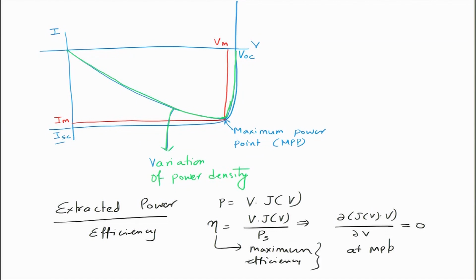Okay. So, this is how these two are going to vary. Your efficiency will also follow a similar kind of curve at this point. So, your efficiency will be maximum corresponding to this point. So, essentially the idea is, that is what we said, IM VM divided by P in, and our idea is to increase this product of IM and VM in the solar cell device.